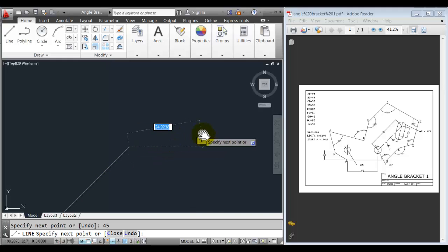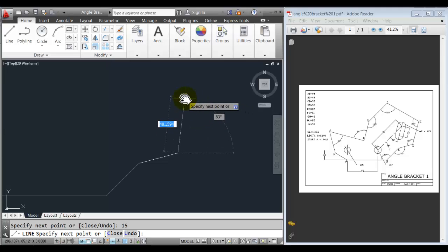And you can see that if I pull my mouse up in this direction, I'm really drawing from straight to the right up. So first we need to type in the length. The length between C and D is 35. Then press tab, and now we can type in the angle that we just calculated to be 15 and enter. Now we should really type in the distance first.